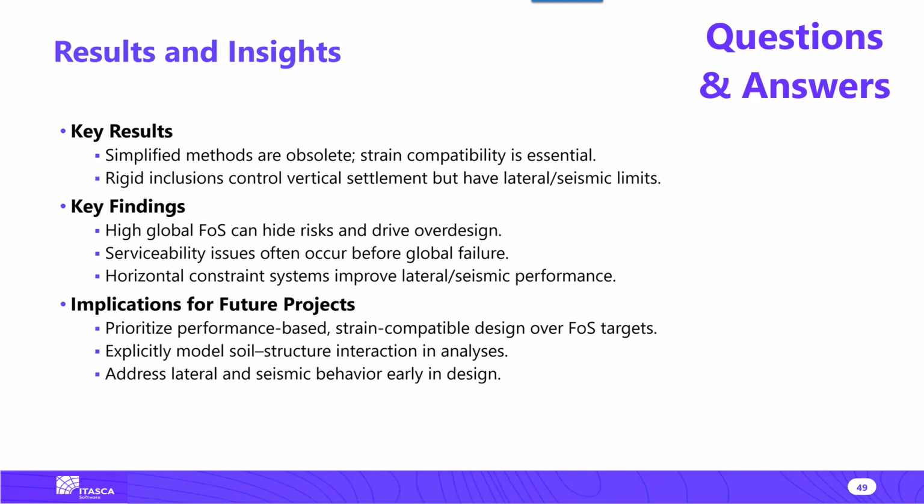If it's steel, it's simple: the yielding of the steel and the elastic modulus. I don't know, it could be wood. Wood could be a little bit more complicated because it is a non-isotropic material. You have different directions. But in general, I've never used wood in any type of application. If we stick with concrete and steel, the properties are relatively simple to get and calibrate.